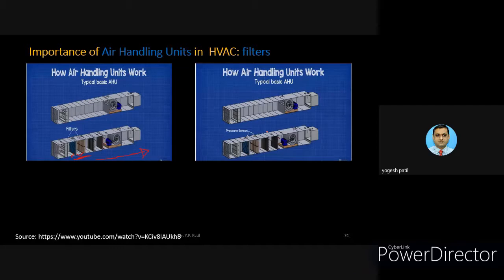Why are those pressure sensors there? That is also the question. So simultaneously we are discussing the operation of that particular part and the importance of the measurement. This will measure how dirty the filters are. Because filters are continuously catching dirt and dust, to know the current situation of the filters, how much they are dirty, it is required to measure with the help of pressure sensors, and particularly that is an indication to the engineers so that it is possible to replace the filters.